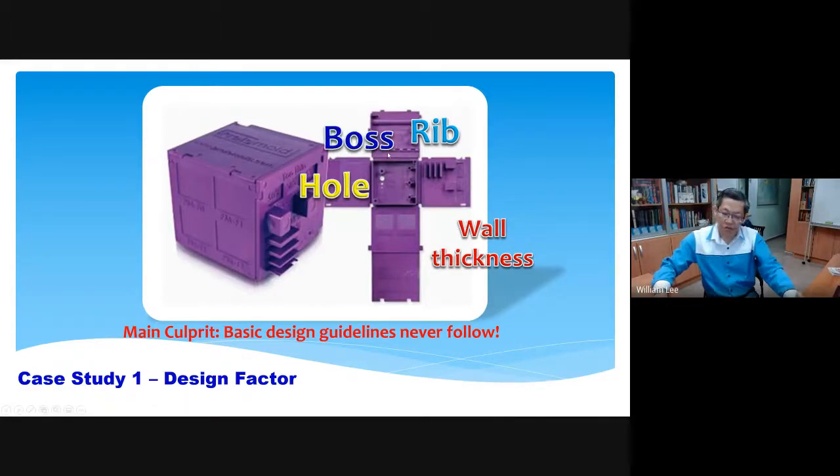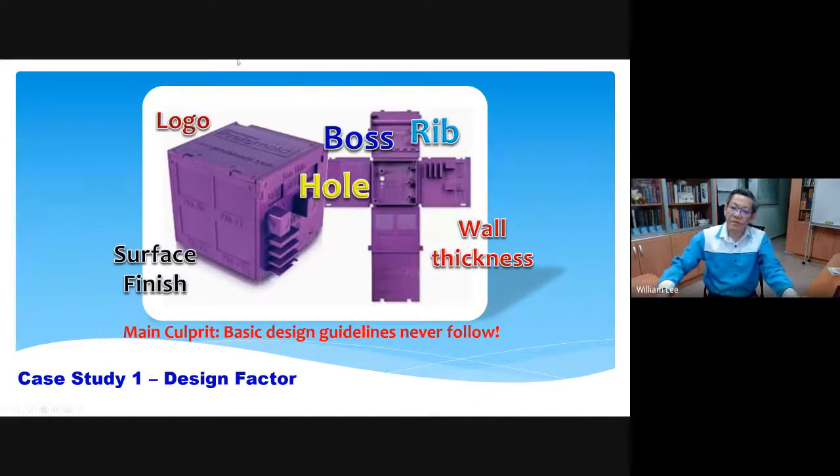boss, not the boss that you are looking for the job. These are the bosses, meant for fastening purposes. And then we have surface finish and even the lettering or logo, plus also the draft angle. So these are the things that you should study, because design is one important factor to improve the molding quality and productivity.